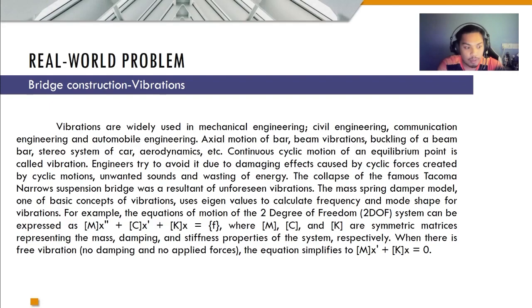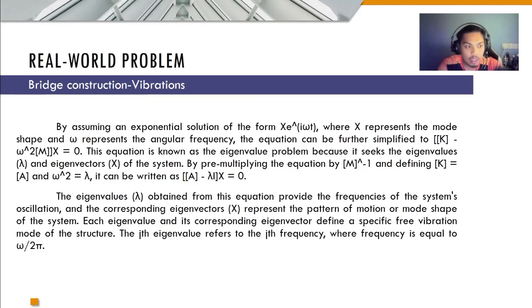Where there is free vibration, no damping, and no applied force, the equation simplifies to Mx'' plus Kx equal to 0. By assuming an exponential solution of the form x e^(iωt), where x represents the mode shape and ω represents the angular frequency, the equation can be further simplified to (K minus ω² M)x equal to 0. This equation is known as the eigenvalue problem because it seeks the eigenvalue λ and eigenvector x of the system.